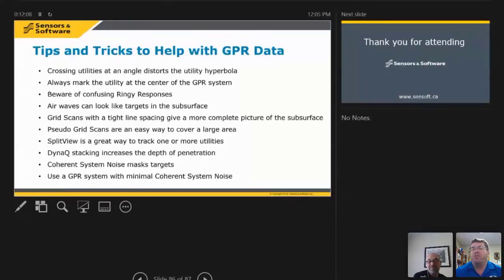Does it reduce the quality of GPR data and/or depth of penetration? Water itself is not going to eliminate GPR signals. Technically, when you get up into the very high frequencies, there is more absorption of GPR signal, above about 500 megahertz. That's the microwave oven effect. A microwave oven is actually a GPR system with a much higher frequency.